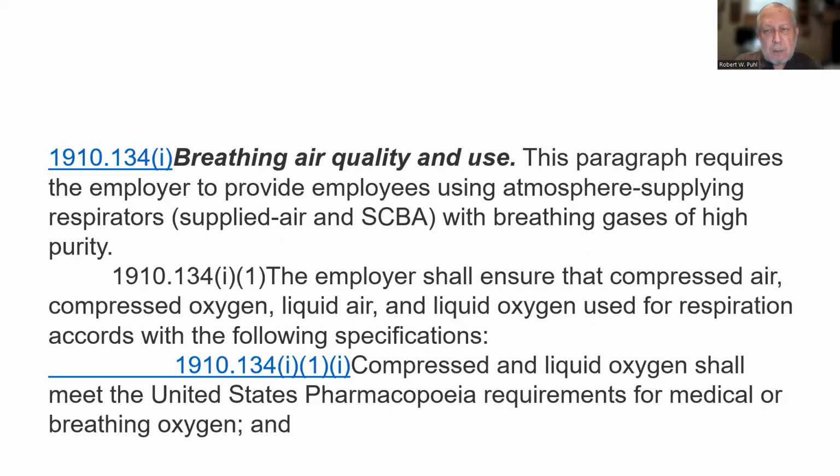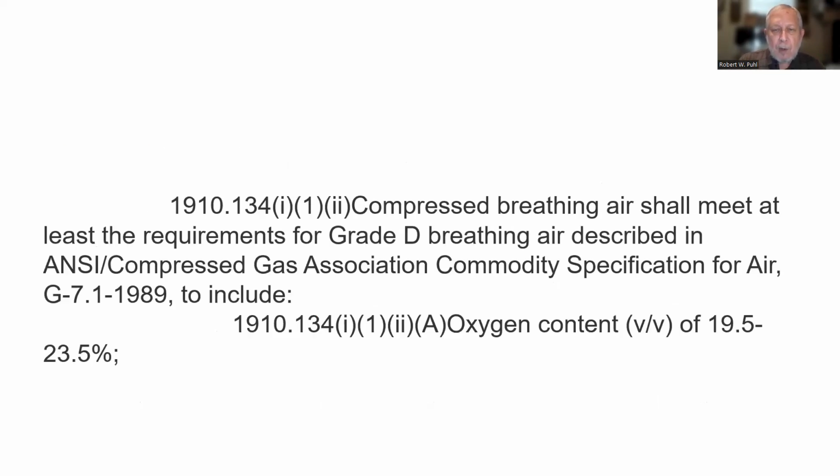Breathing air quality and use. This paragraph requires the employer to provide employees using atmosphere-supplying respirators, supplied air and SCBA, with breathing gases of high purity. The employer shall ensure that compressed air, compressed oxygen, liquid air, and liquid oxygen used for respiration accords with the following specifications. Compressed and liquid oxygen shall meet the United States Pharmacopoeia requirements for medical and breathing oxygen, and compressed breathing air shall meet at least the requirements for grade D breathing air described in the ANSI Compressed Gas Association commodity specification for air,